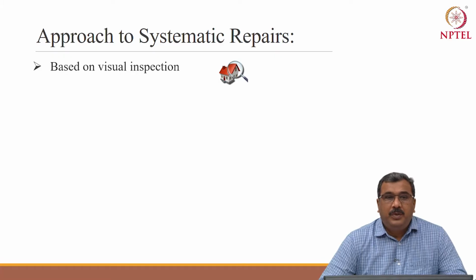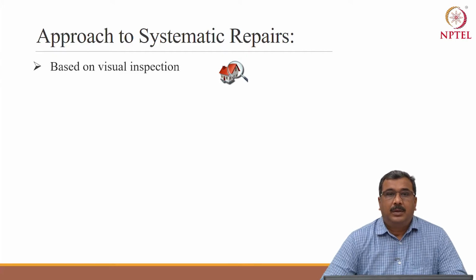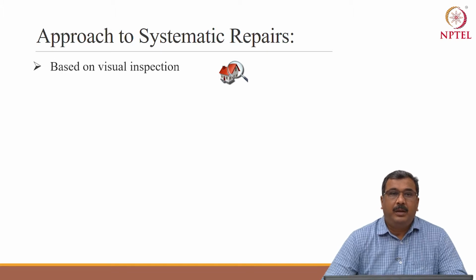You need to observe the structure properly. Carefully see the pattern of the cracks, alignments, signs of leakages, color of the building concrete, corrosion marks, how particularly such defects are on one face, another face, bottom of the building, settlement of the building.